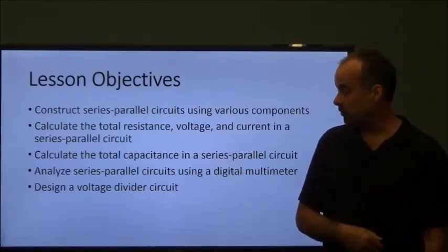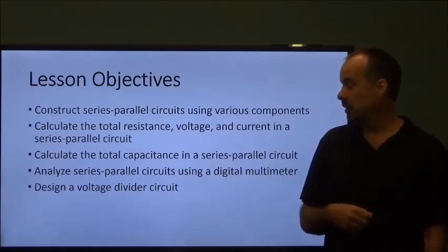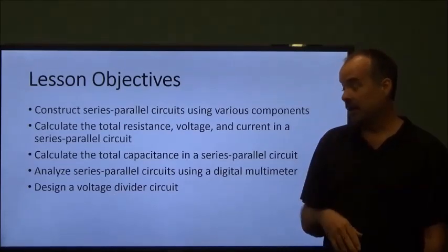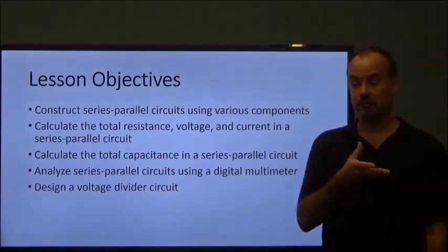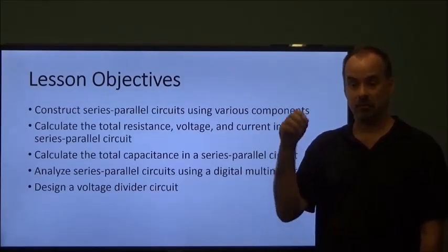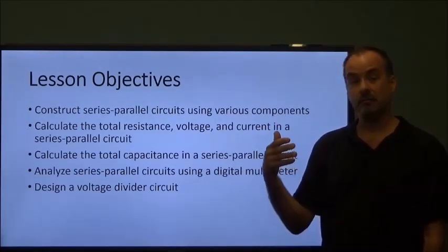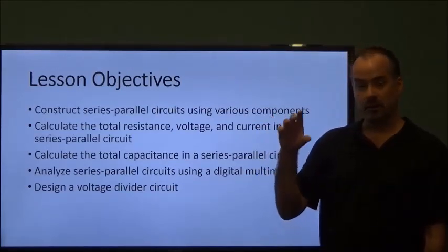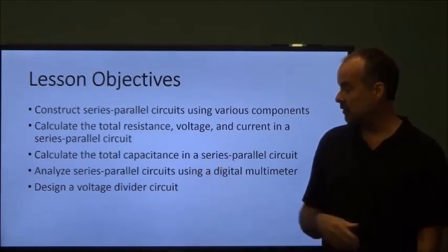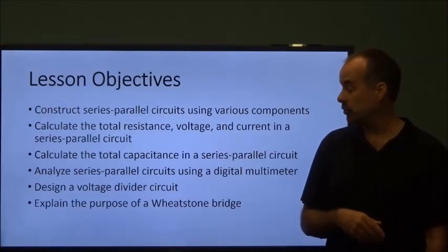You'll be designing a voltage divider circuit. Again, that's in the online content. The textbook goes into an explanation of the purpose of a voltage divider circuit, how to construct them, and what they're used for. Essentially, if you have a given power supply voltage, say it's 24 volts, and you need 24 volts in one part of the circuit and 5 volts in another part of the circuit, you can design a voltage divider network that has different voltages at different points, and so you can use those in other parts of the circuit. But like I said, the textbook goes into a pretty good explanation of what a voltage divider circuit is and what they're used for.